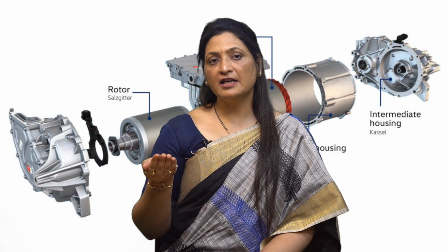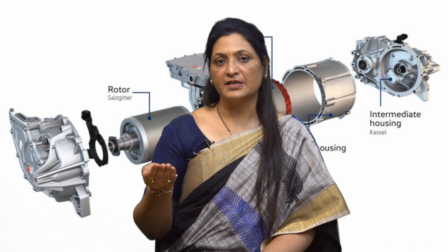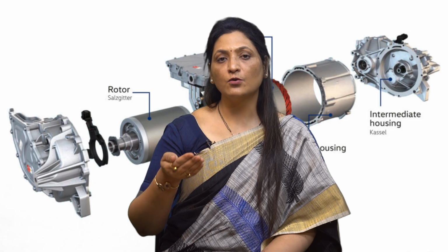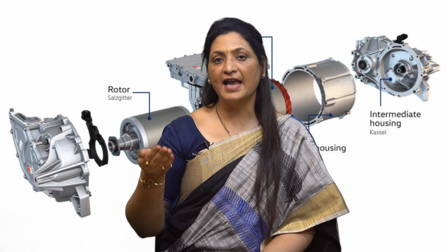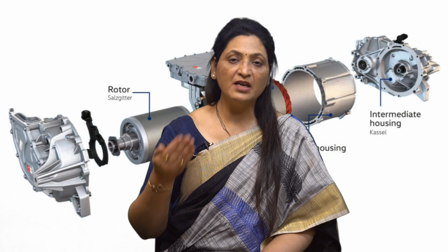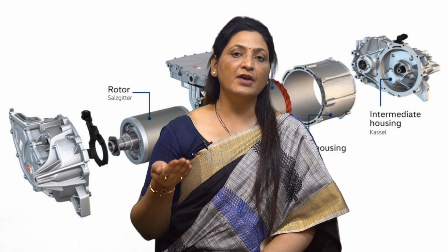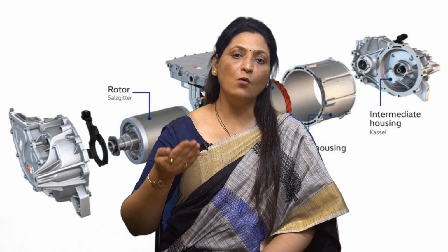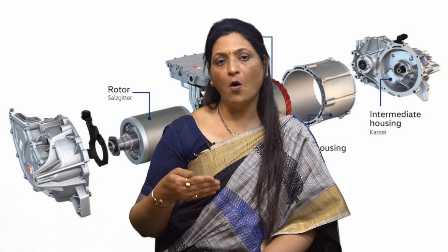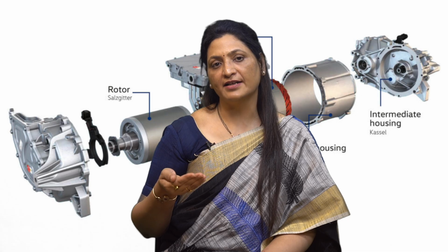The second class is the variable impedances. The variable resistors are commonly used for control of low cost DC and AC drives and are also needed for the dynamic braking of the drives. Variable resistors may have two or more steps and can be controlled manually or automatically with the help of contactors.